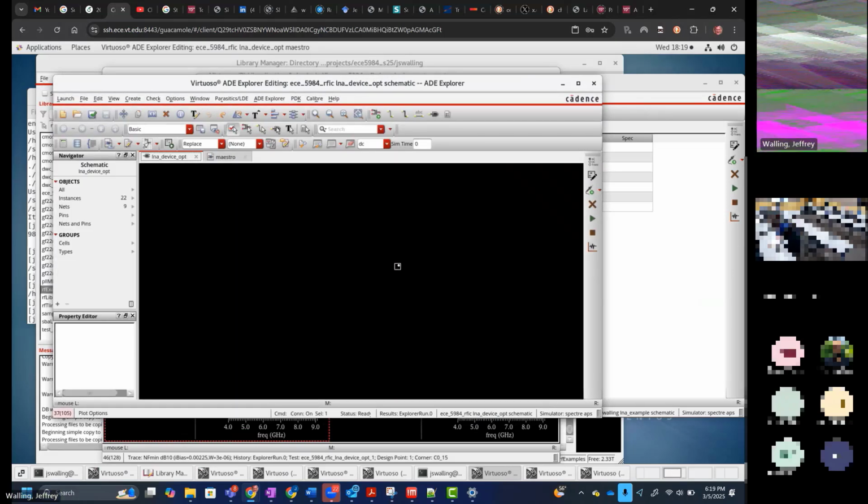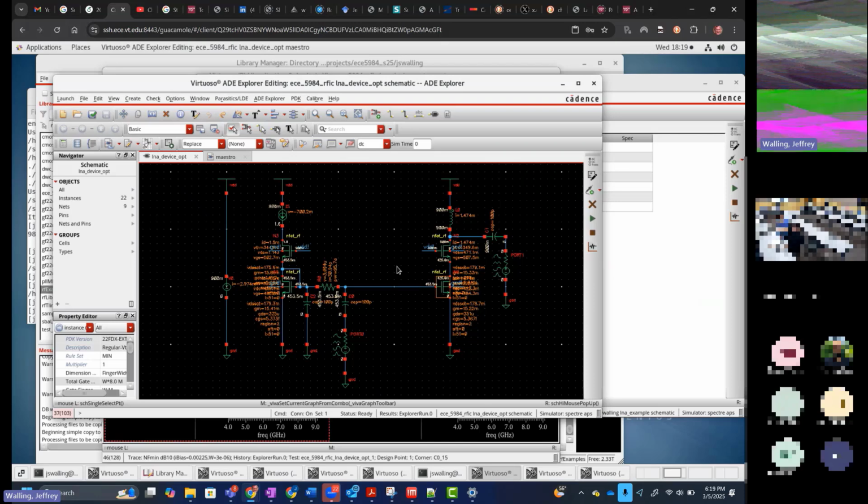So we're making a U-turn. We're going to talk about LNAs for just a few moments. Here is a simple LNA topology. I am basically making a current mirror to bias the LNA. So the LNA devices are these ones on the right side, and these devices are just a reference voltage generator to generate the bias voltage for the LNA.